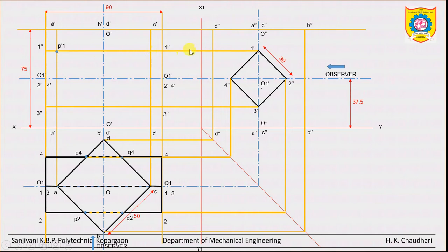Because it is lying on this projection number 1, and here in the top view, the projection taken from 1 is this, and it intersects the vertical prism at this point A. So the vertical projection from point number 1 and the horizontal projection from point number 1 is named P-1.